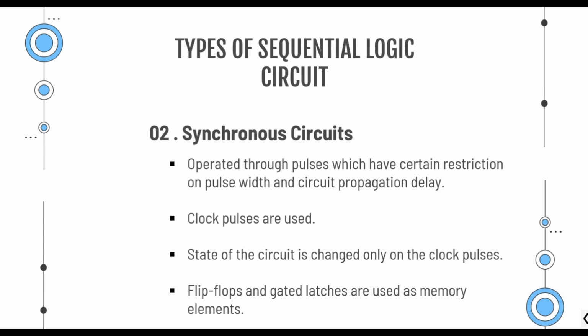Another disadvantage is that synchronous circuits generate waste heat. The clock signals must be distributed to every memory container in the circuit, and this clock signal is usually a high frequency signal. This distribution consumes a comparatively large amount of power and generates much heat. Even memory containers like flip-flops that are doing nothing consume a small amount of power, thereby generating waste heat in the chip.